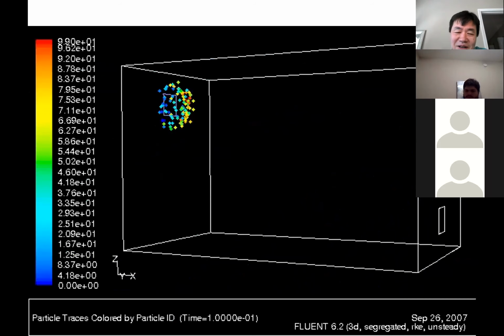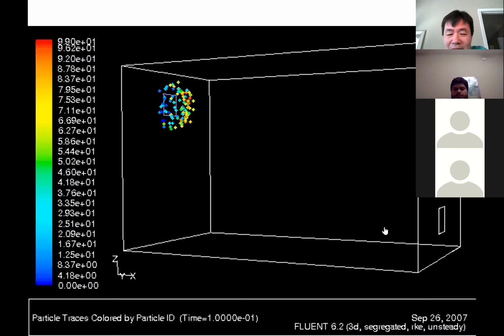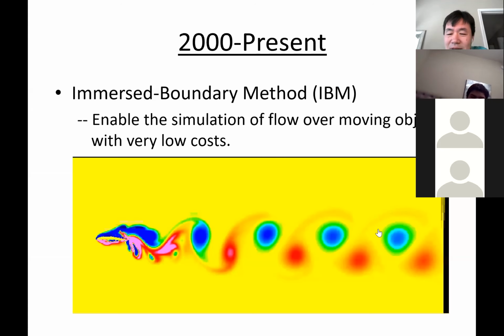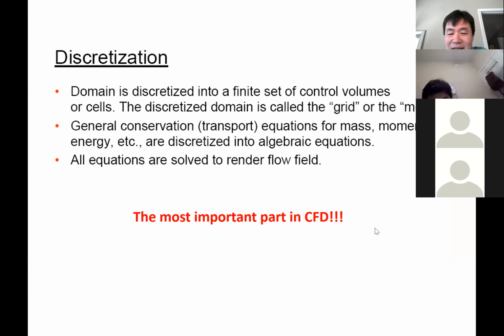Okay, anyway, we can look at this rocket, for example. You see very small flow structures near the fin of the rocket, see? Kind of more complicated, but far away from it, it's just free flow, just airflow, right? So it's not that complicated. The complexity is caused by the presence of the object. That's why in reality, when we create the mesh, you want to make sure. Fluent usually will do it automatically, but sometimes it makes a mistake. Okay, it's not guaranteed.